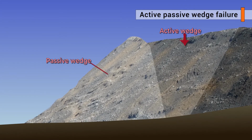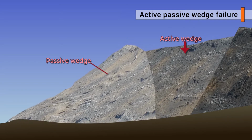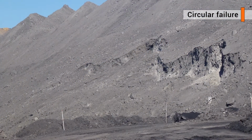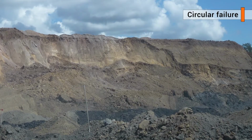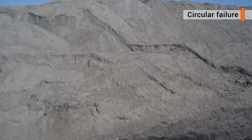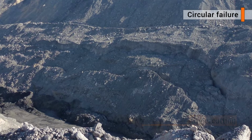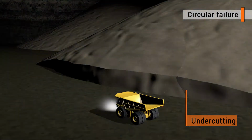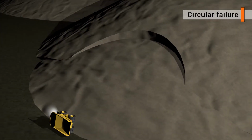Active-passive wedge failures. These type of failures occur in dumped slopes, particularly where the dump is formed on a weak and/or steeply dipping floor. Circular failures. Circular failures occur in highly weathered, soil-like or dumped material that contains little to no large rock fragments. Circular failures may be deep-seated or may occur near the surface, where they are referred to as skin slippage failures. Circular failures typically result from an excavated or dumped slope that is greater than the angle of repose through undercutting or over-steepening mining practices.